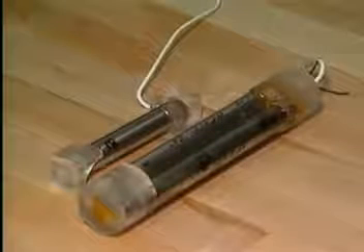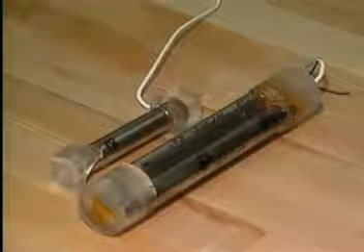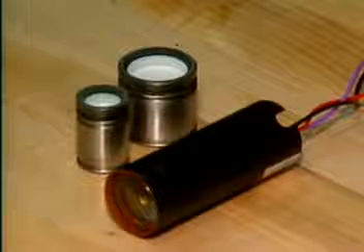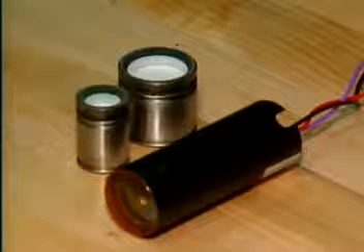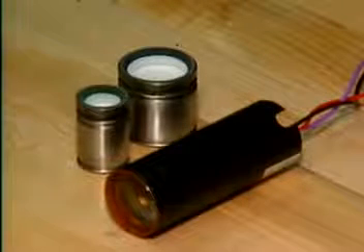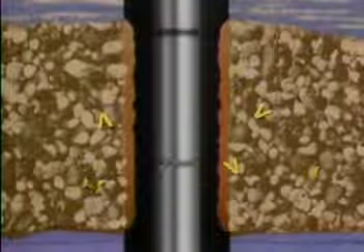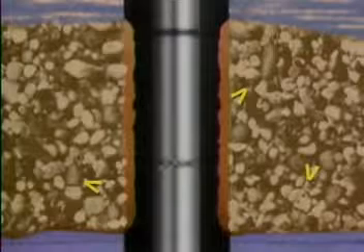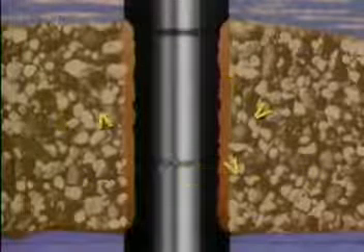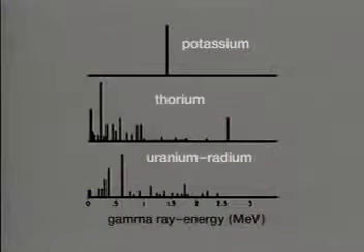The conventional gamma ray tool consists of a Geiger-Müller counter or a more sensitive sodium iodide scintillation detector and crystal, which counts natural gamma ray emissions for fixed intervals of time. These emissions originate through the natural decay of radioactive elements in the formation surrounding the borehole. The radioactive elements are due primarily to uranium, thorium, and potassium.